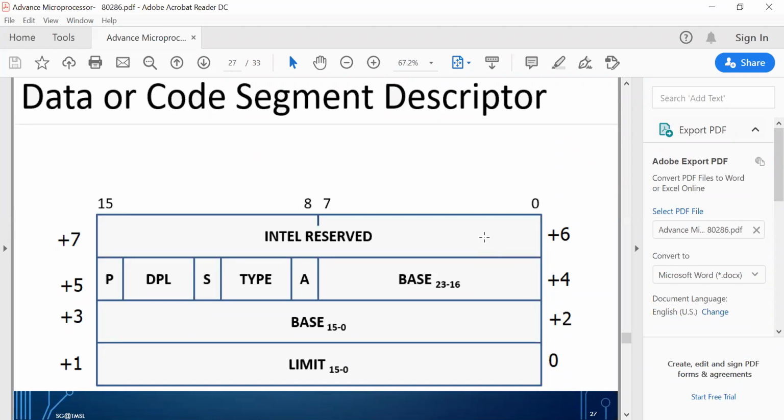For accessing any program, segment, or page, its descriptor is first accessed, and its access rights byte contents are verified with those of the requesting program. Now, if the contents of the access rights byte allow, only then can the requesting program access the program segment corresponding to the descriptor.